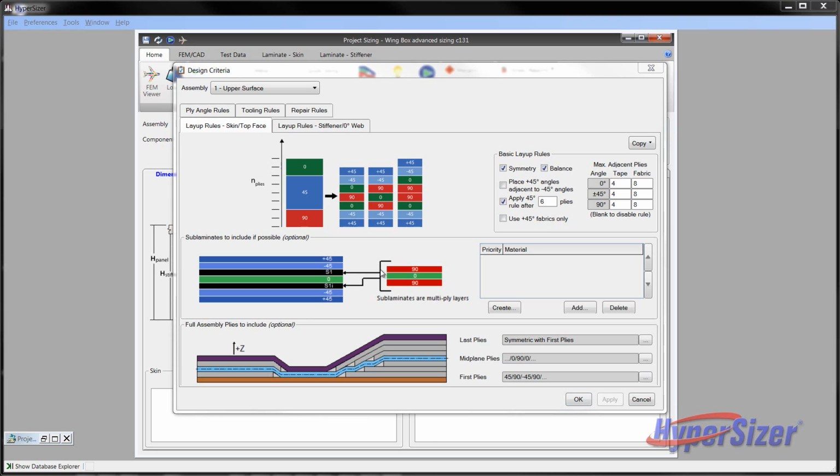The rest of the form provides a way to specify how the laminates are to be stacked with full body plies for the assembly. As such, they are meant for fabricating more producible parts. The sublaminate is another method used to reduce cost by purchasing layers of materials as a unit that speeds layup on the tool.